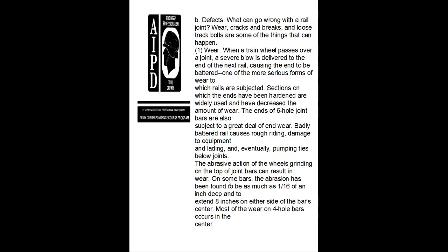Sections on which the ends have been hardened or widened only decrease the amount of wear. The ends of the 6-hole joint bars are also subject to a great deal of wear. Badly battered rail ends cause rough riding, damage to the equipment, and eventually pumping ties below the joints. The abrasive action of the wheels grinding on the top of the joint bars will result in wear, sometimes found to be as much as 1/16 of an inch deep and extending 8 inches into either side of the bar center. In most of the wear on 4-hole bars, it occurs in the center.